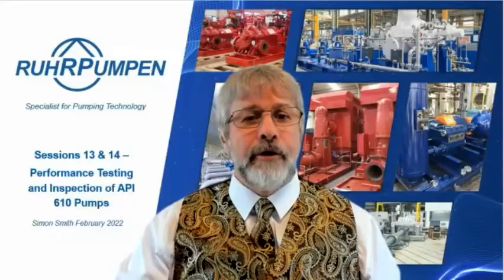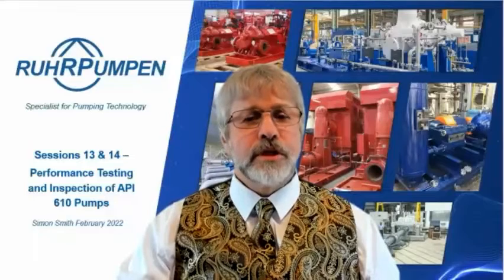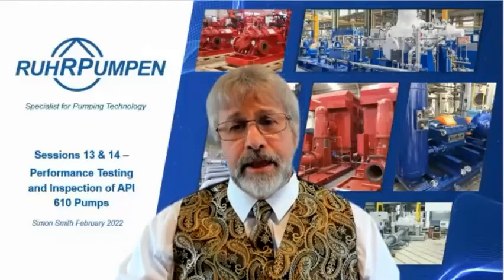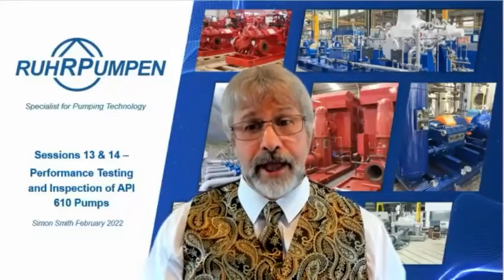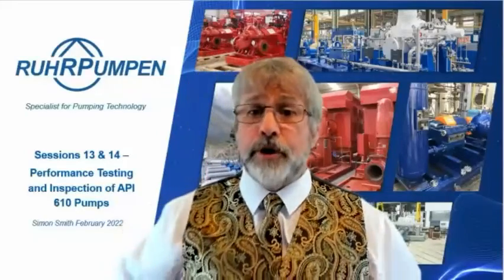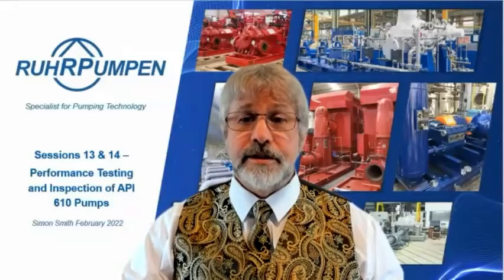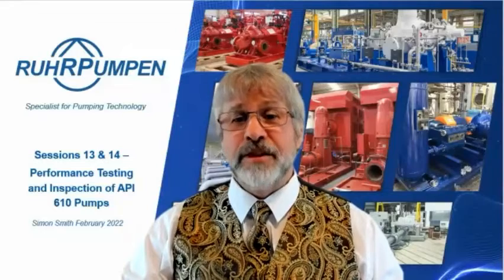Carlos Mallow, how do you carry out the bump test? The pump connected to the piping in the shop, pump full of water. Okay, the bump test for a bearing housing, it doesn't matter because you're just bump testing the bearing housing. The pump, I think, is disconnected from piping when you do this one. I think that's specified in API 610. And similarly, the natural resonant frequency test is done with an empty pump just on the nozzle head of the pump in the performance test loop.